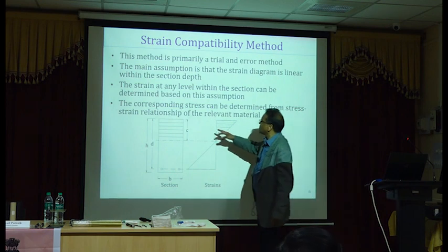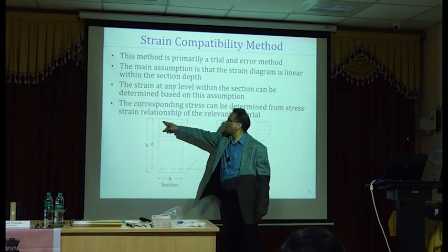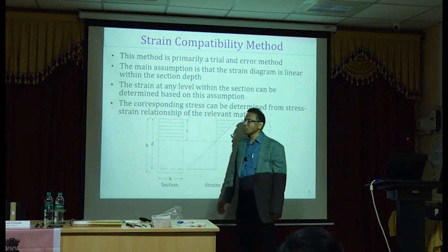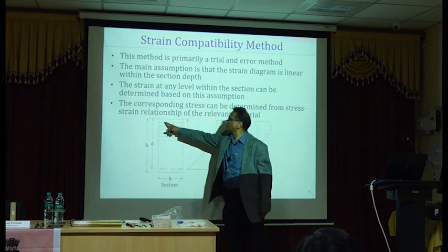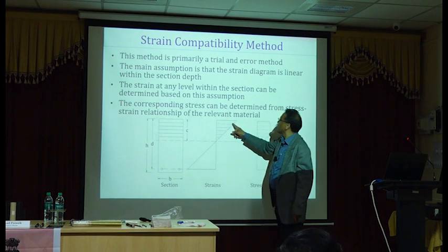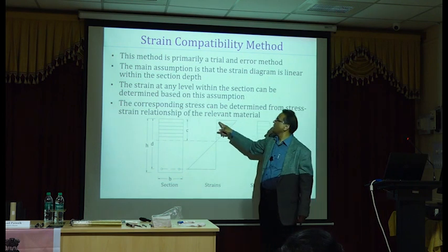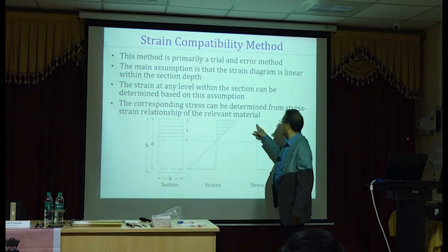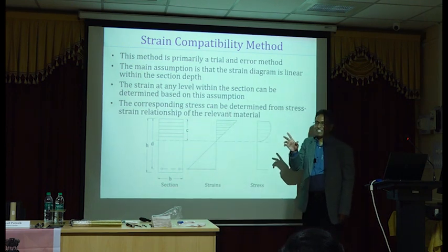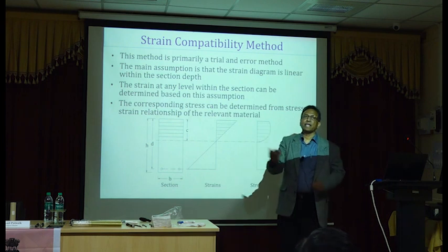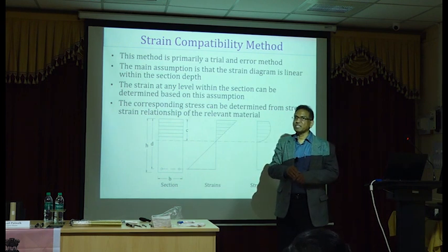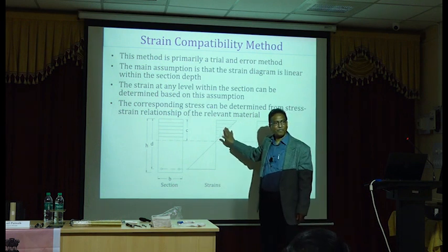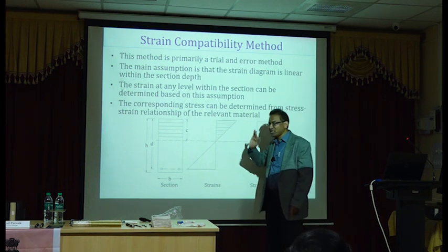If you have reinforcement here, steel reinforcement or FRP reinforcement, of course we won't use FRP reinforcement in compression areas, but if you have steel reinforcement, you can find the strain at the level of the steel reinforcement, and you can also find the stress corresponding to the strain you find from the strain diagram. Make sense? Step by step.